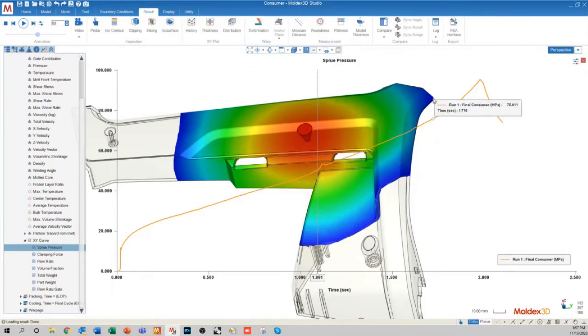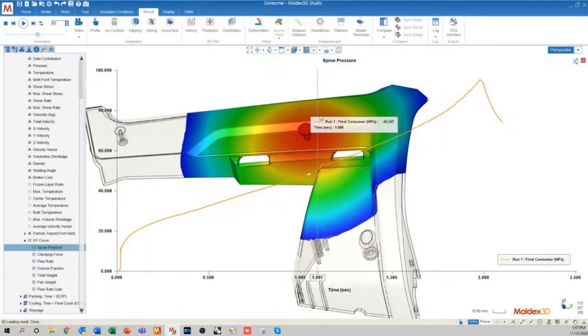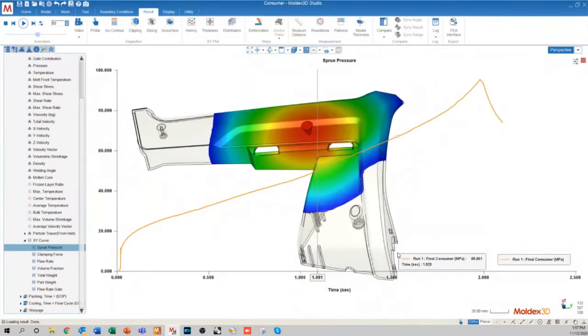So what you can think of is that melt is hitting a wall, and now it has to bounce back and go in either this direction or this direction. We call this a momentum shift of the flow of the plastic. If that momentum shift actually happens through the gate, that's where we get these little spikes, or in an extreme scenario, if maybe this end of fill over here occurs before the end of fill down at the bottom